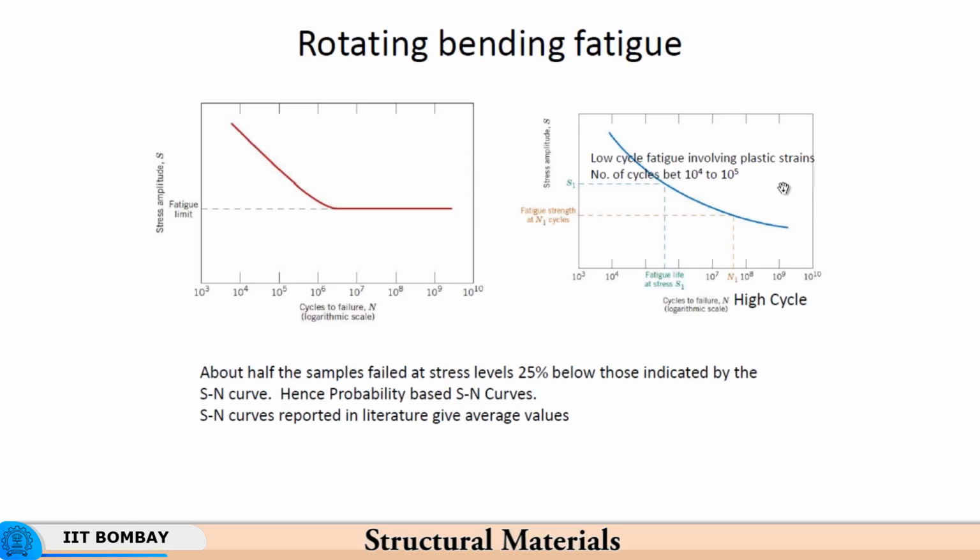So, usually in low cycle fatigue you have plastic deformation. Plastic deformation leads to accumulated strains, as I just explained, and these accumulated strains result in accumulated damage, and then the crack propagation becomes easier, and therefore the final failure under fatigue cycles happens at much smaller loads.